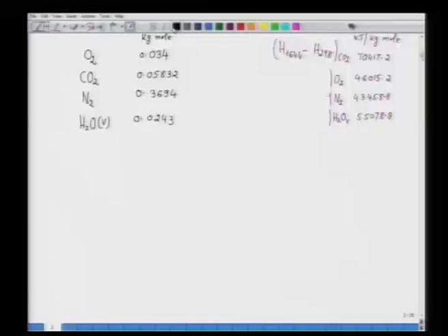Why? Because the calorific value of fuel given is the net calorific value, where the standard state of the products of combustion of H to H2O is the vapor state. That is the important thing. Now, once we know the heat content values, then I can calculate from here.